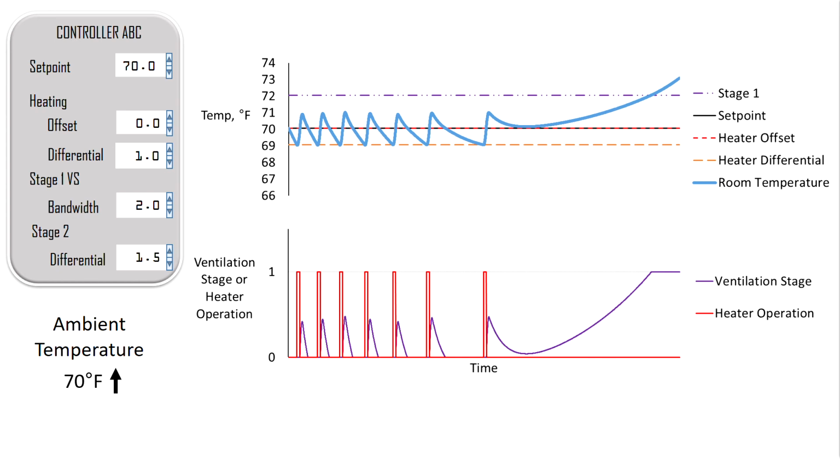What you notice in this simulation is that we have the heater and variable speed fans trying to compensate for one another. This is largely a result of that overshoot we talked about, both by the heating system, but also to an extent by the ventilation system. We do not have any buffer space in our settings to use this overshoot to our advantage. What happens if we make one small adjustment on our controller?